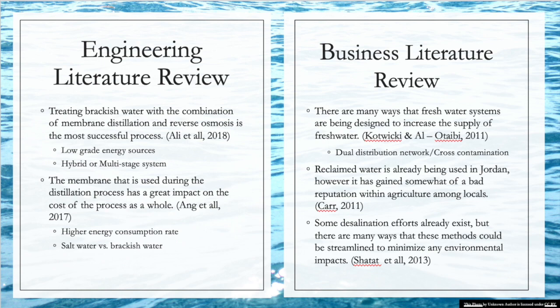When treating brackish water with the combination of membrane distillation and reverse osmosis, desalination efforts are much more successful. Through brine recycling and cascading, there are many different ways to improve the recovery rate and ensure that the driving force doesn't decrease. Using a low-grade energy source integrates a renewable energy source into the desalination process, which can make this process have a smaller environmental footprint.